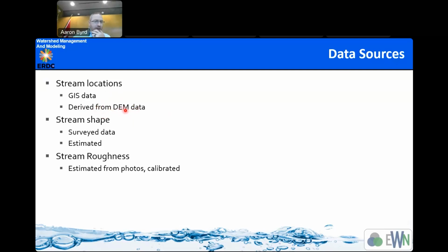It usually works best if we just start from the DEM model, then they work together. And you can pull in the NHD data set as just a background layer to check, okay, am I getting my streams roughly the right order of magnitude in the right spots, that sort of thing.